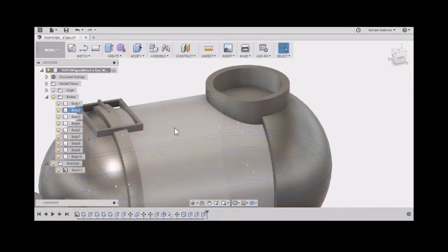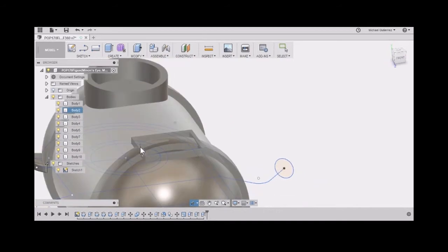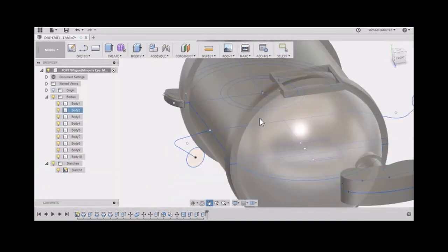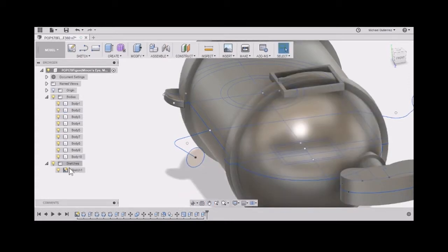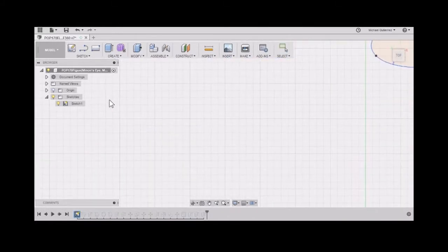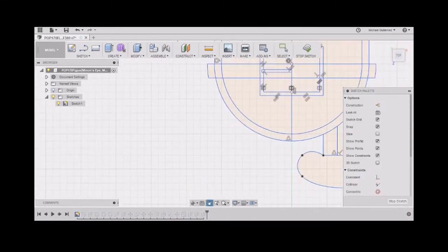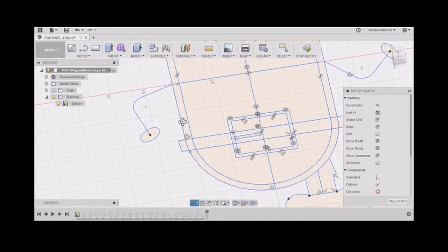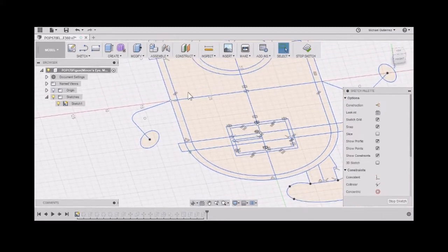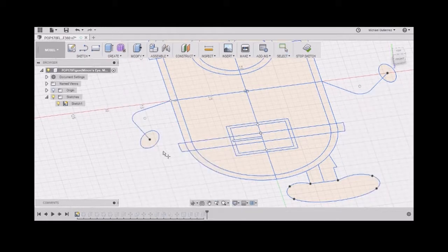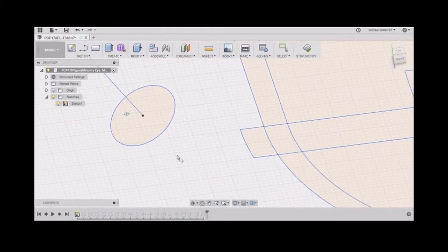Alright then. Now we're going to do the arms before we do the eyeball. And there's a reason for that. The reason is that when you go to the sketch, right click it and hit edit sketch. Now if you notice, all of the bodies have this here, that's fine because we're editing the sketch. And that's what we need to do the arm. So I'm going to orbit a little bit, go to create, and I need to do spheres. So both arms right here and just here.